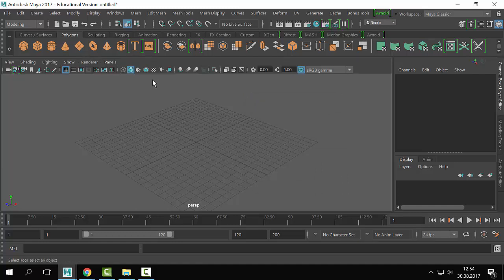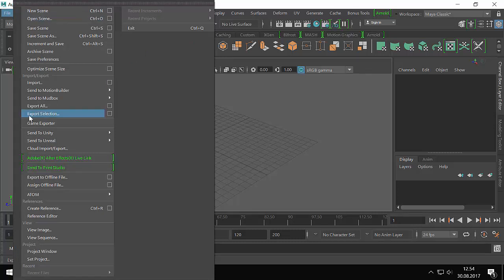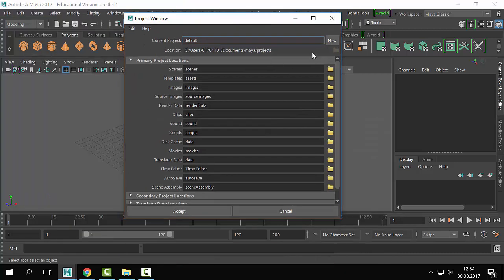When you start out in Maya, anything you do, and I have to mention this every time, I will be mentioning it over and over again, we always set a project. So you need to get into the habit right away. File, Project, and then I will set the path for my project. So I can say this will be lecture.